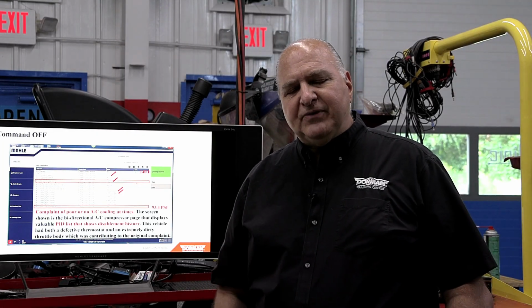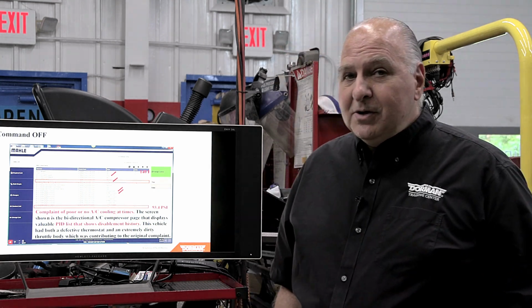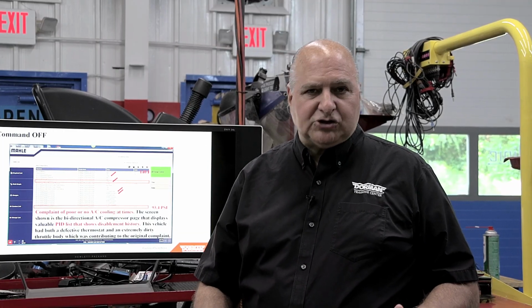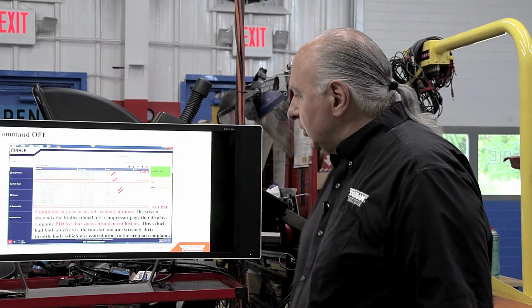Well, do you realize even a power steering switch on many vehicles, when you go to parallel park, well, you say, who does that? Well, in the New York City area, we have to do that, right? And when you cut that wheel hard, guess what? That's a load on the motor. That could help cut the compressor out if they think it's too far of an extra load, especially if it's a cycling compressor.